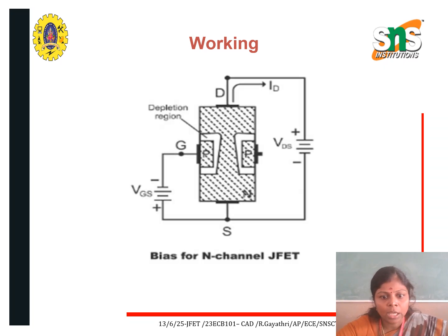And coming to the working of the N-channel, the gate terminal is negative with respect to the source terminal, and the drain terminal is positive with respect to the source terminal. When we are giving the gate voltage VGS, when VGS is equal to 0, a lower amount of current will be flowing from drain to source terminal. When we keep on increasing our VGS value,